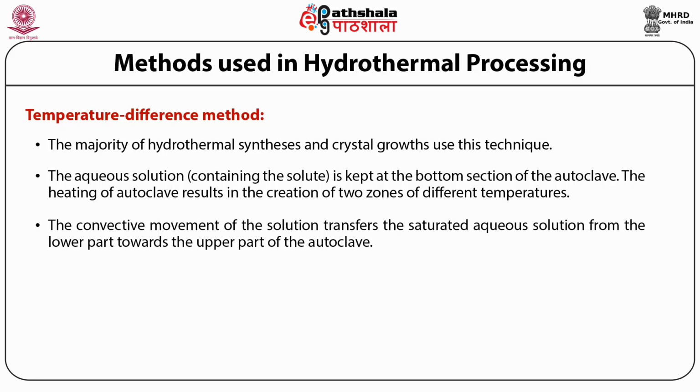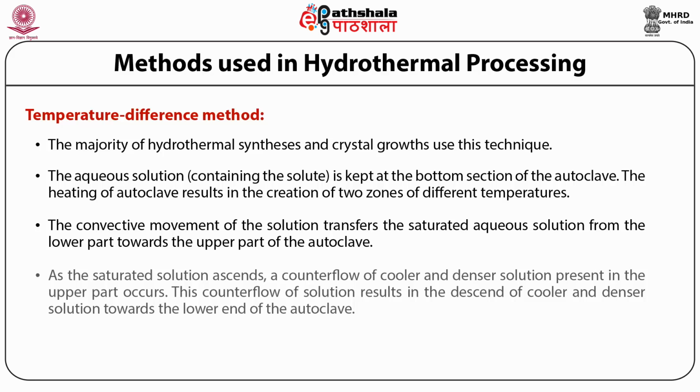The convective movement of the solution transfers the saturated aqueous solution from the lower part towards the upper part of the autoclave. As the saturated solution ascends, a counterflow of cooler and denser solution present in the upper part occurs.